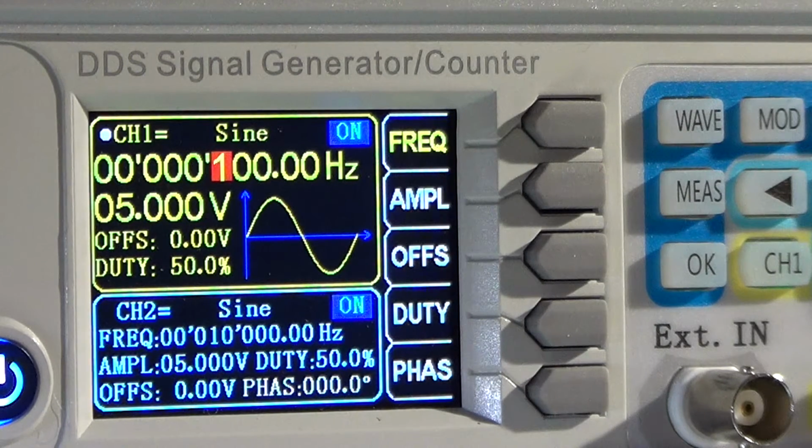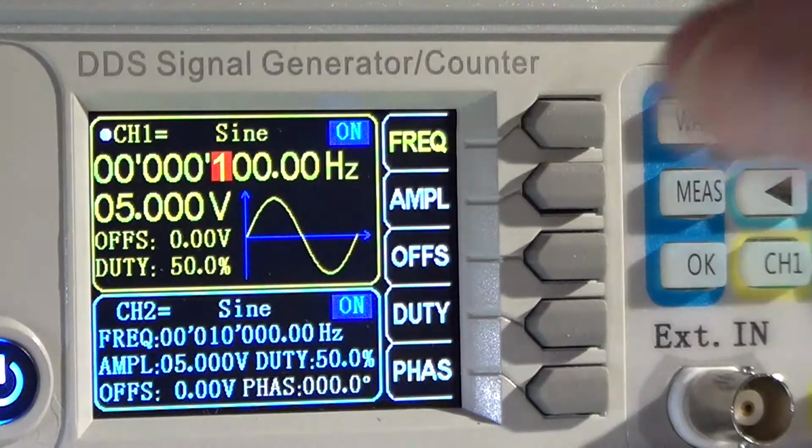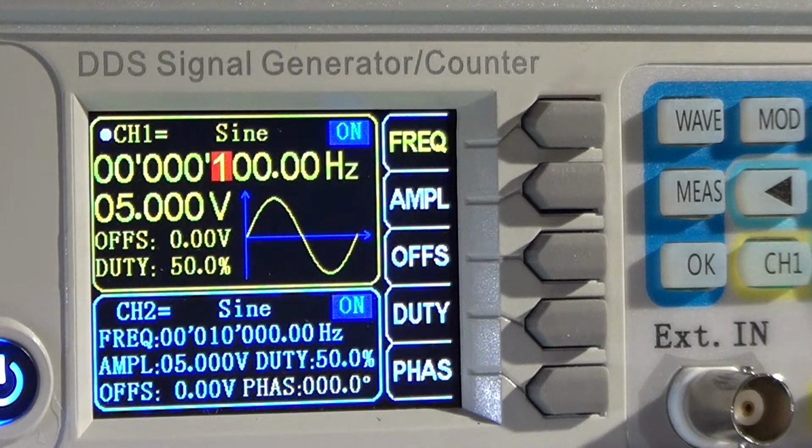Rather than using the oscilloscope in the frequency domain, we will do it in the time domain, and we will basically measure the moment where the 5 volts are reduced by about 1 over square root of 2, which is basically the minus 3 dB that we are looking for, defined as the drop in magnitude of the signal at the cutoff frequency.